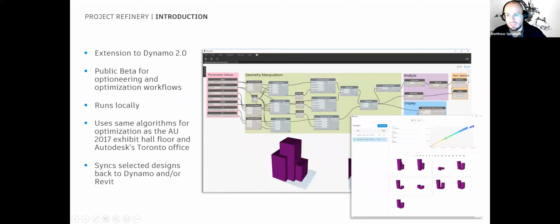When I usually lay out designs in Dynamo for generative design, I like to break it down where I have all my inputs, my parameter values, and all of my preferred metrics or performance metrics at the end. And then analysis and display and geometry is somewhere in the middle.